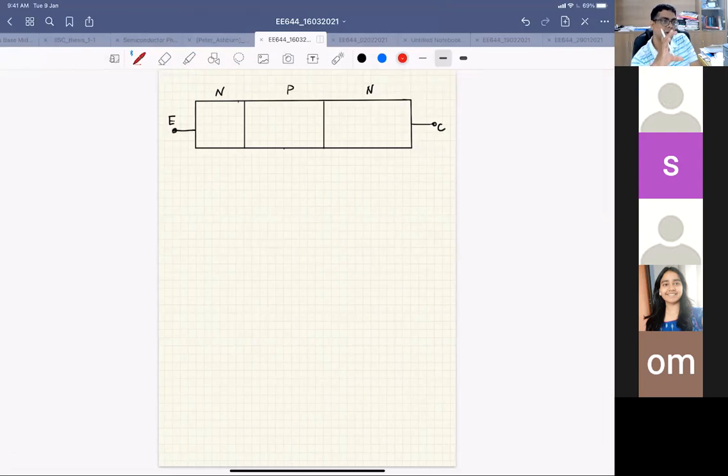We want to see the maximum output voltage that you could give. That's why BVCEO is important. In BVCEO the base is open. You could think of it as shorting the emitter, the base is open, and then you apply a voltage at the collector.